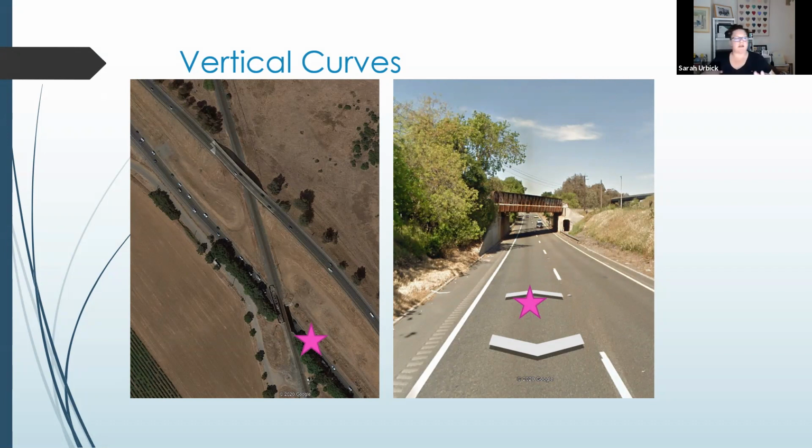Most of the time they need to scrape it. Kenny, you're correct. So we mill it out, we grind out portions of the material in order to meet those existing conditions and maintain certain grades and certain drainage profiles. One thing you'll see here and on this side, you see that kind of lighter color? It's because the bridge decks are concrete. So we'll put asphalt on top of existing materials, and then you have this concrete transition to the concrete bridge. That's a lot harder to grind off.